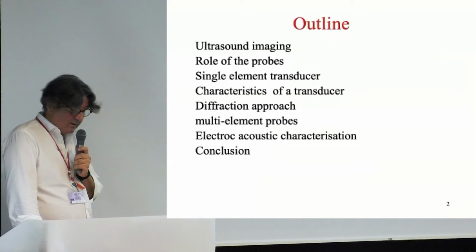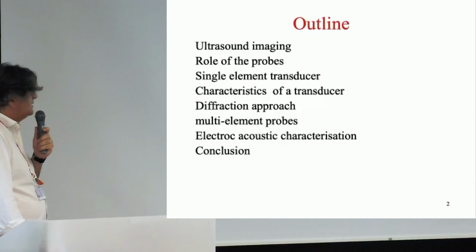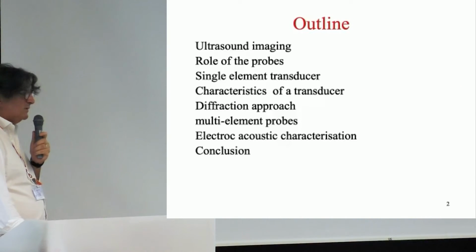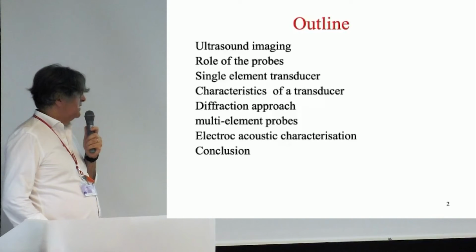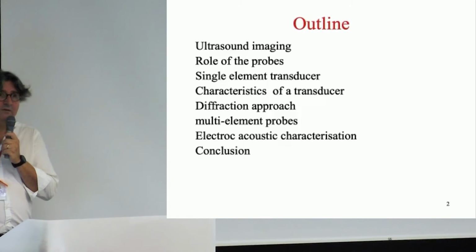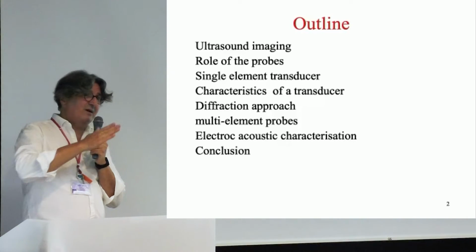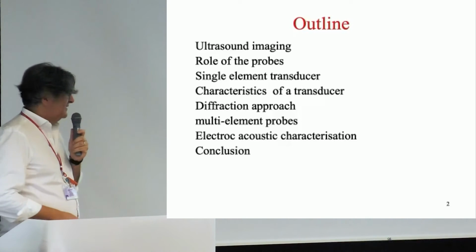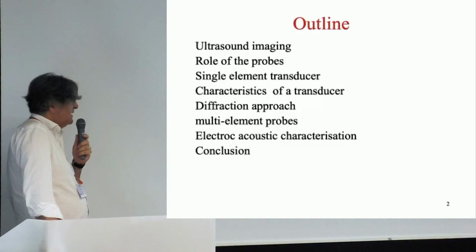So in this talk, we will talk about ultrasound imaging and the role of the probes. We will talk about single element transducers, the characteristics of a transducer we have already talked about. We will go more deeply into detail in the diffraction approach, and we will use some acoustic results to analyze the diffraction pattern of transducers.